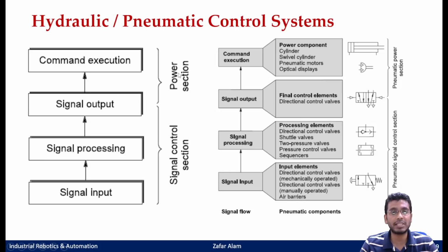That means the power section in both the cases, okay, remains the same. That means your single acting cylinder and your double acting cylinder, and your fluid power, be it your compressed air or your pressurized fluid, they both are going to remain the same. Your signal control section or your signal processing, these would change. Instead of doing it with all these type of valves, they will all be done using electrical signals.